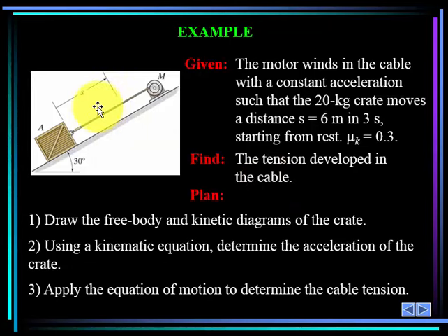And if we know cable tension, then that would allow us in a next step that we're not going to do, to talk about motor torque and motor speed, and would allow us to talk about motor power. And from all of that, we would be able to choose the motor out of a catalog somewhere to be able to get this job done, because we would know torque, speed, and power. And we'd get to decide whether or not we need a gearbox to make this motor work.